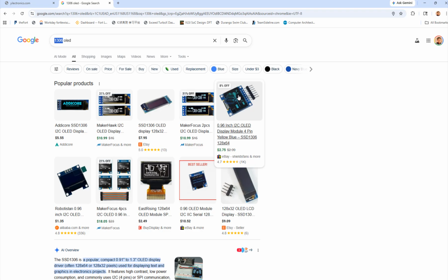The students soldered their own PCBs. So the signals were amplified, right? And they used their on-chip ADC, which is XADC, which we're going to cover today, on the FPGA, to digitize that signal. With the SPI module on the FPGA, it communicates with the follower, which is the SPI module on the Arduino chip.